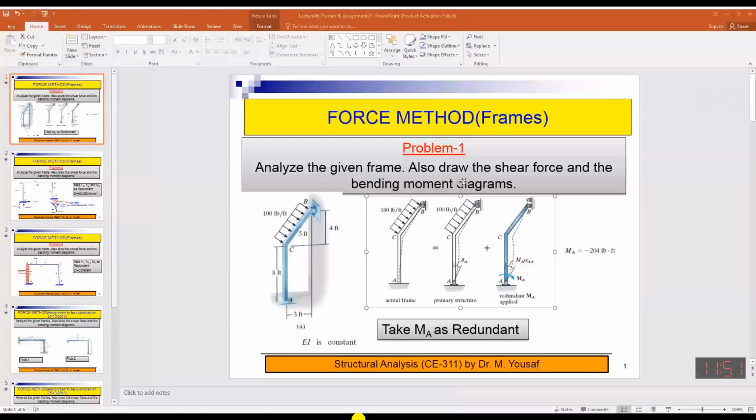And this is the primary structure. For this primary structure, you will have to find out the reactions at this location, at this location, and at this location. Now, this is 100. This is total 5. So total reaction will be 500. Now 500, if this is to be converted according to global axis, now this is acting perpendicular to this local axis. This is local axis, this is x-axis and this is y-axis for local. Now this force is acting along the local axis.